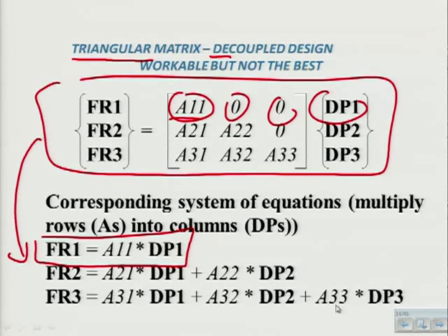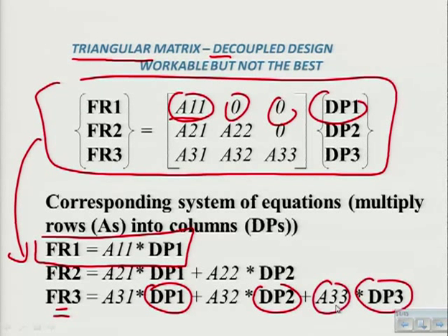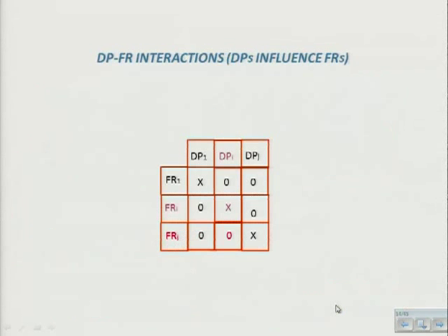And so in the order of adjustment, I've done something to dP1, that's changed FR3, then I've done something else to dP2, that's changed FR3 again. Who knows if it's going to be within tolerance or not? It doesn't matter, because now I can adjust dP3, and A33 will tell me how that's going. dP3 is going to influence FR3 and bring that back into tolerance, despite the fact that dP1 and dP2 may have taken it away from where it needed to be.